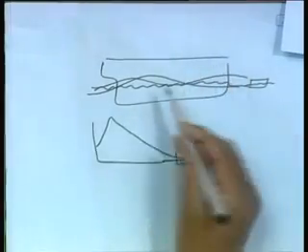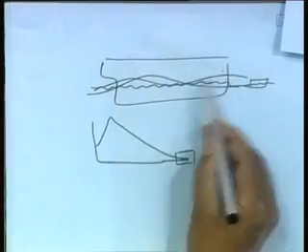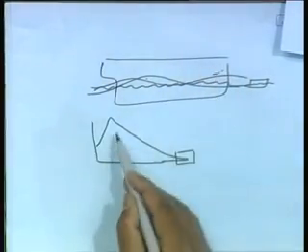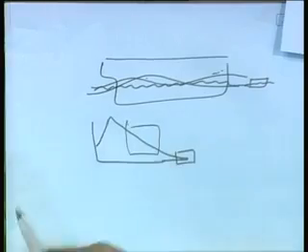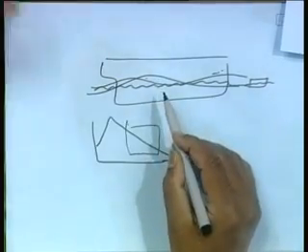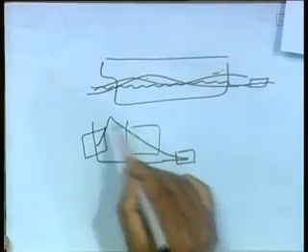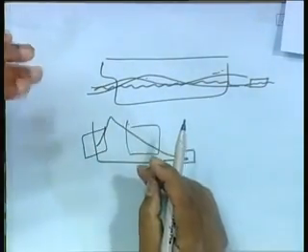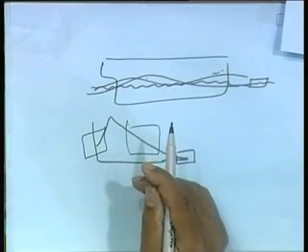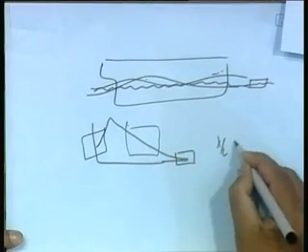And of course, in the open ocean these things always happen, and in this case these motions are in this region, we are shifting to this region. Remember, for a 300 meter long ship to go to this region I need a 1 kilometer long wave, that means lambda by L to be 3.